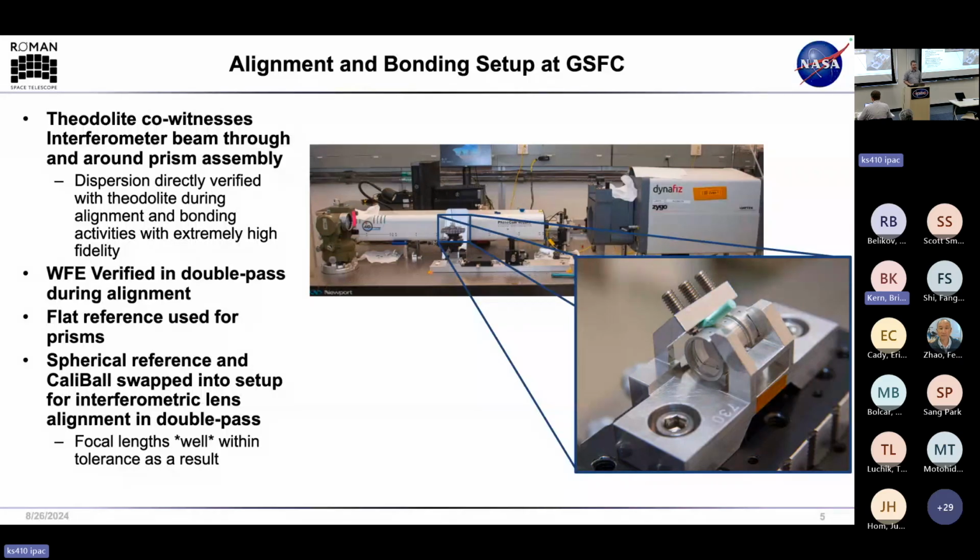Just one quick note on the optical alignment. We accomplished this. We had very tight tolerances on everything, in particular our back focal distance. There's no focus mechanism on the back side of CGI. So we had to guarantee confocality of all of the imaging assemblies in the DPAM to an extremely tight tolerance, much tighter than the F number would lead you to believe. Gary was a real stickler about that.